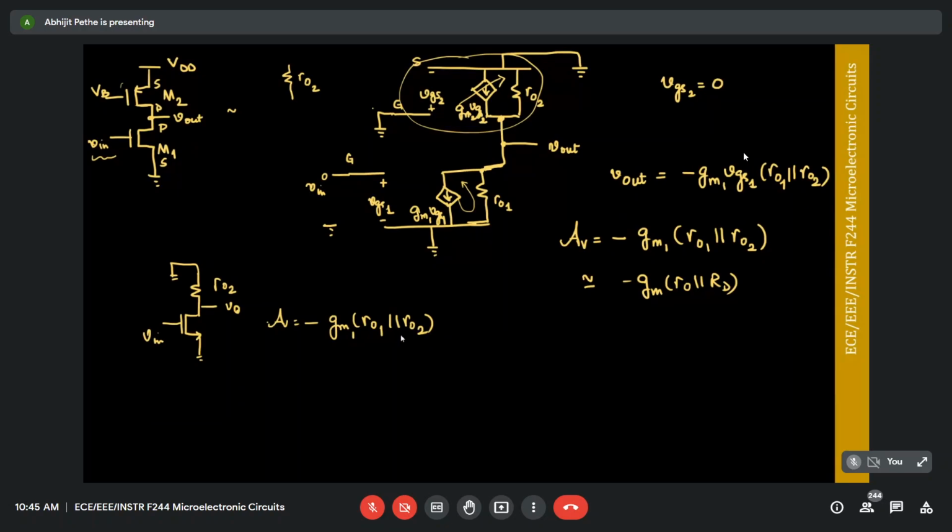So that is how you analyze circuits, because later on we'll quickly ramp up to larger circuits. So then you won't have time to keep doing these small signal analyses and replace 5 transistors with these small signal models. So understanding that this amplification is happening because this NMOS is converting the voltage to a current, and that current is flowing through a combination of two resistors, RO1 and RO2, leads to a gain given by gm1 times RO1 parallel RO2.